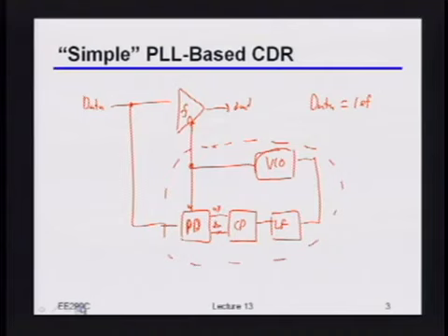Okay? Now, there are many different ways you can imagine to do this. Historically, the first way that people typically would use is the so-called PLL-based CDR. The basic idea was very similar to what we just said before, except that now for that phase adjustment circuit, we would use a voltage-controlled oscillator rather than some other possible method. The issue with doing this was that this VCO, especially if you want a pretty wide tuning range so you can cover lots of different possible data rates, tends to be pretty dirty, meaning it has quite a bit of jitter.